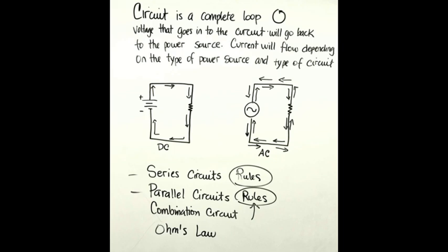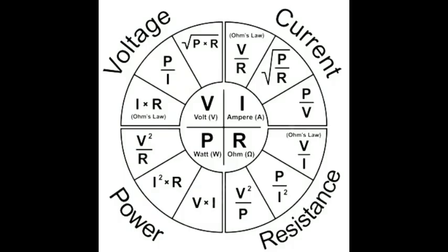Now here, I can go ahead and use Ohm's law, right? I remember that my voltage is a constant value, so I can insert 40 volts to all of them to be able to get the amps and to be able to get the power of each one of these resistors. But I like to finish my totals when I have enough values.